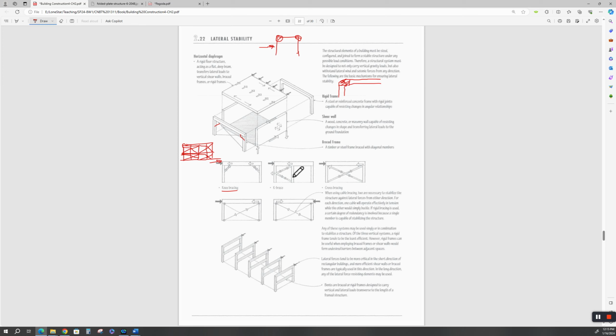Okay, K-brace. Why is it called a K-brace? Because it looks like a K. And it works in the same manner. All right, there you go. Wind's going to push on that. One of these is in compression. One of these is in tension with this particular loading. Column has to resist it this way, and the upper beam or the roof deck, the rigid diaphragm, resisting in that direction. Again, we want equilibrium, right? Newton's third law, opposite and equal reactions.